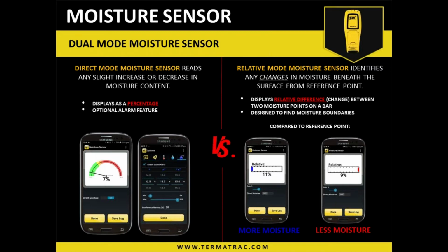It's very easy to do. The 3 little dots above the white screen open the options. We turn on the alerts via the checkbox, and then we adjust the 3 numbers for low, medium, and high settings, whatever you determine to be an issue with moisture.